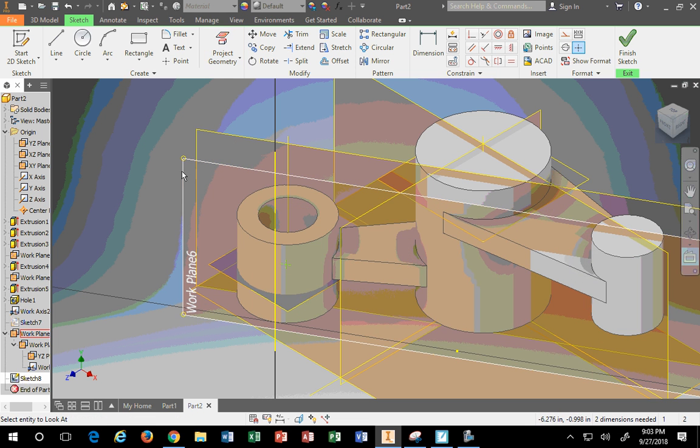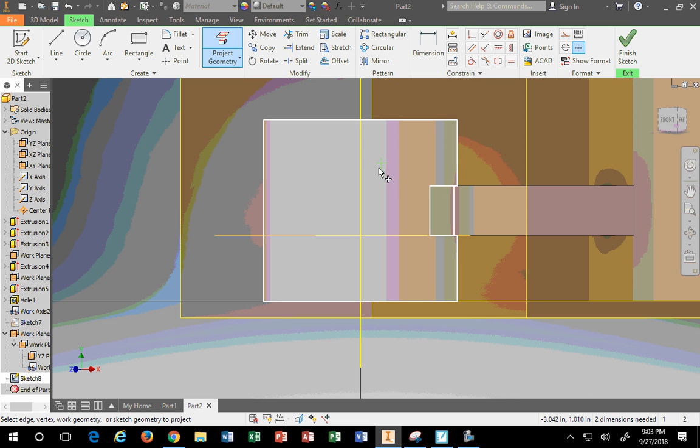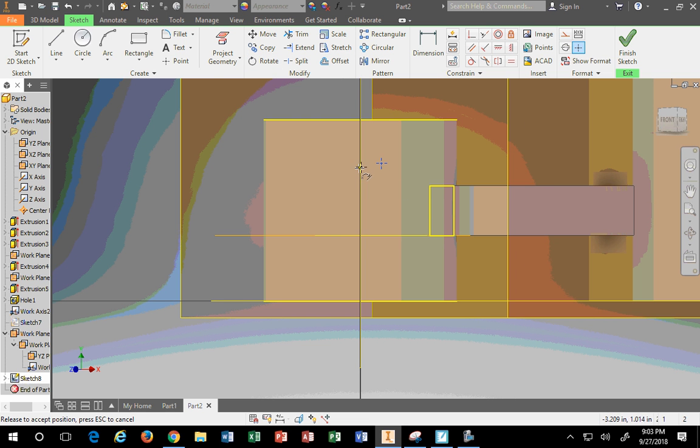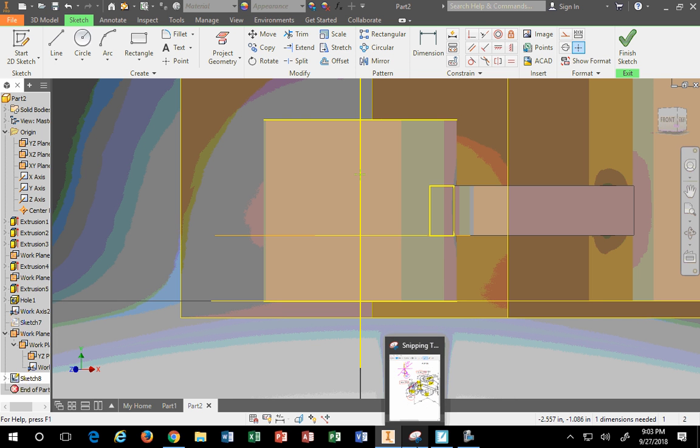Once you project that center, let's get out of the project geometry command first, my mistake, then I can take this little cross and drag it over so it touches it and locks onto it. The next thing I need to add is where vertically, because now this little point moves up and down. Where do I lock it in vertically? Again, remember there's more than one way to build this. I'm just showing you one method. Where can I lock this in vertically?